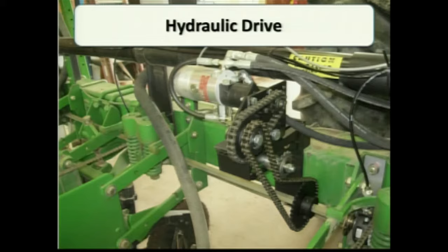We're taking that mechanical drive that has a bunch of gears, throwing the hydraulic drive in. You got to have the display. Typically, what we call an electronic control unit will sit between this, just a box that has your wiring harness plugged into, and that electronic control unit communicates between the display and a hydraulic motor to drive what the exact rate is that you want to put out.